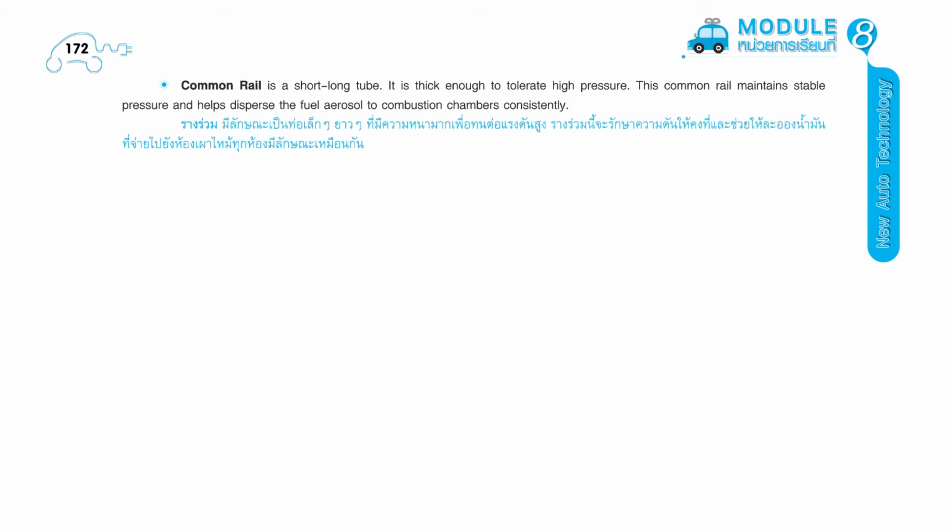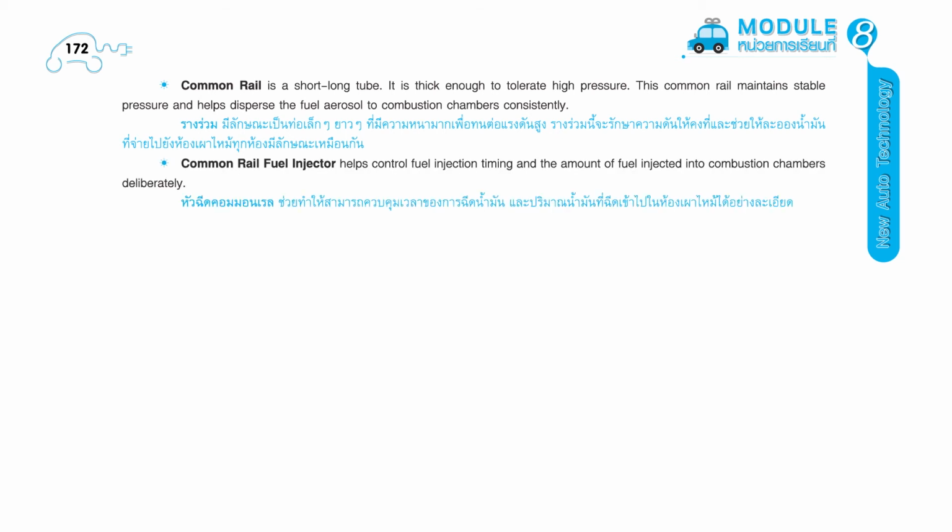Page 172. The common rail is a short, thick tube. It is thick enough to tolerate high pressure. This common rail maintains stable pressure and helps disperse the fuel aerosol to the combustion chambers consistently. The common rail fuel injector helps control fuel injection timing and the amount of fuel injected into the combustion chambers deliberately.